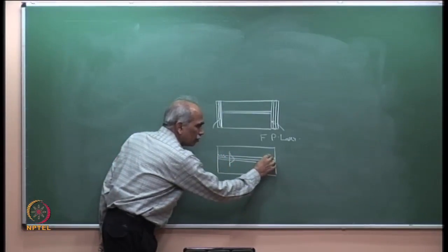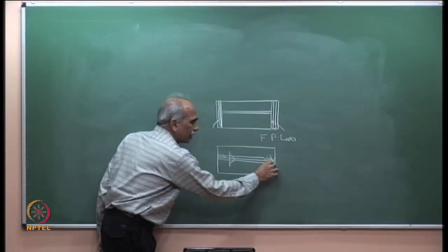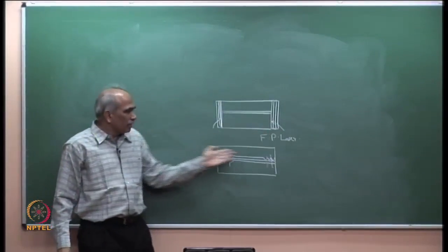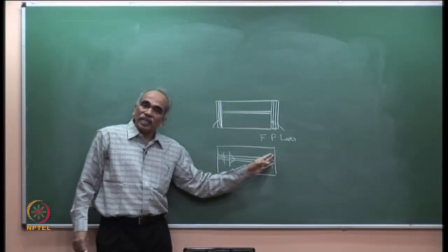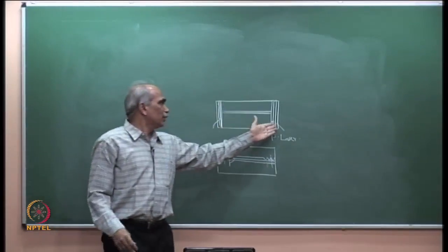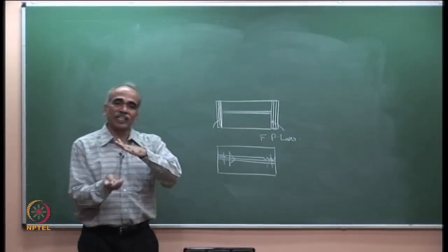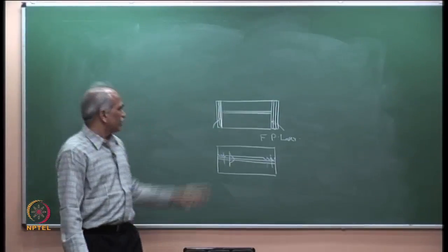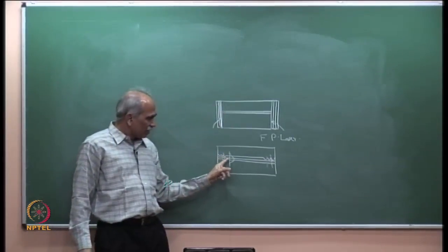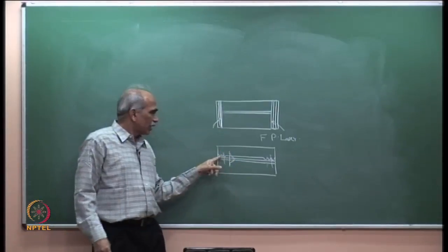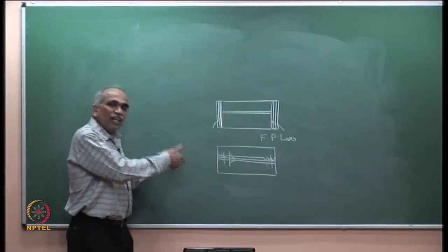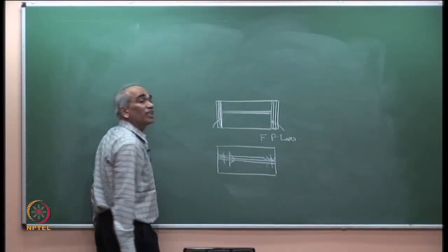At the ends, there is a frequency selective grating here. It is not a separate bulk layer, but it is within this. This can be much more easily fabricated by lithography. In a practical situation, taking the wafer like this and depositing interference layers is a very cumbersome process, and therefore this is a monolithic process, that is, on the surface you can do lithography and epitaxy. That is etching and regrowth, both are required, but it is a much easier solution.